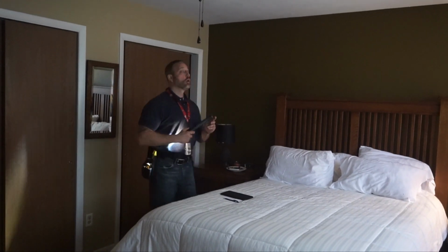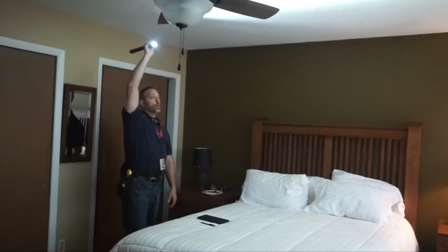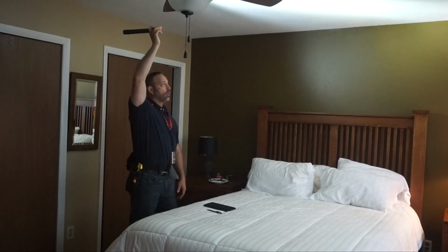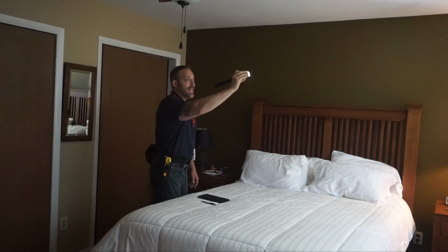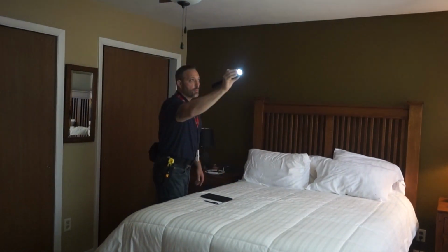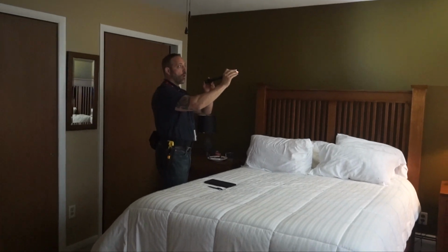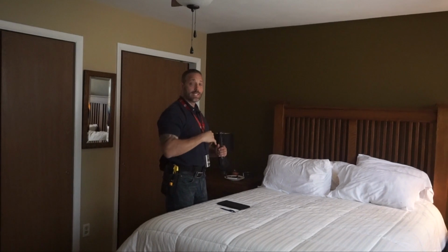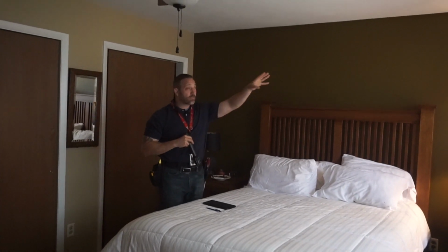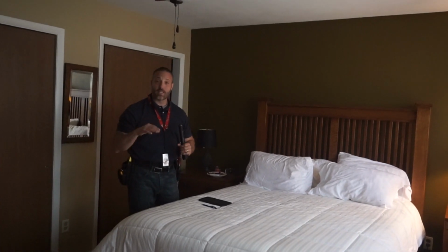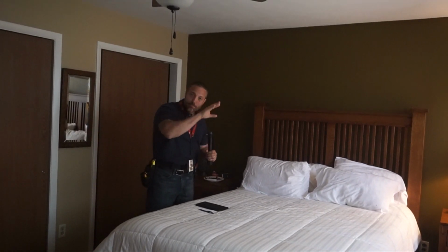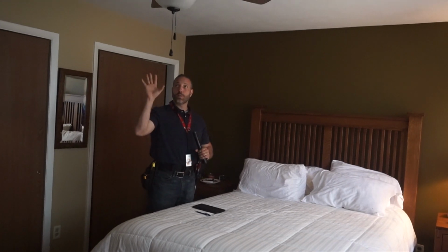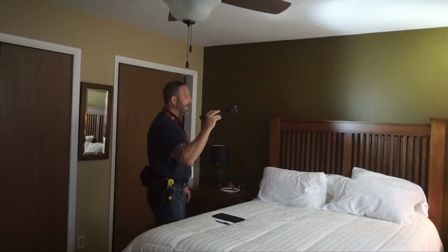So once again, we're going to look at the ceiling and we're looking to see if there's any water staining due to the second floor, or possibly as we look at the joints. At the eaves, we want to make sure there is no water staining, because what could happen is you can have ice damming, which would leak water into those locations. And specifically, you're looking to see if there's any peeling sheetrock tape, or maybe bubbling of sheetrock tape, or stains themselves.